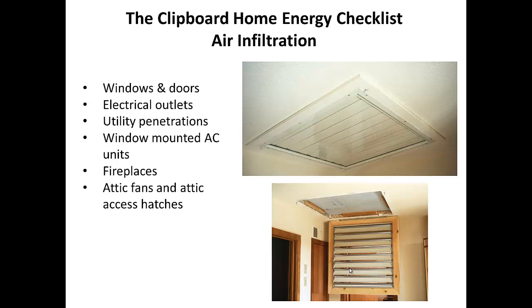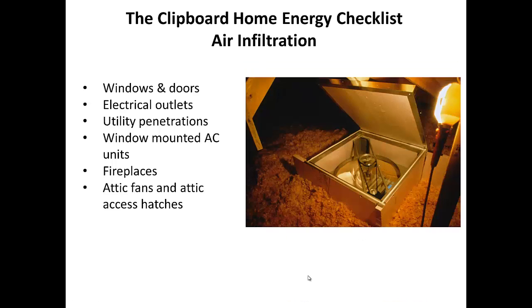Attic fans and attic access hatches. This is in a home that I built. We had an attic fan up there. I like to use attic fans, but boy, in the wintertime, they lose lots of heat that comes down through it. So what I did was create a styrofoam cork, if you will. This was on a piano hinge, and I would drop it down into the down position, and then once a year I would put this cork up there, use weather stripping to make it airtight, and then I'd take it down in the summertime so I could use my attic fan and cool my house down at night, and then close my house up during the day.